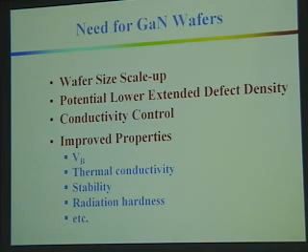Furthermore, the sapphire is not conducting, so both contacts have to be made from the top side. That requires more use of real estate. Therefore, you get fewer die per chip. The stress, the bowing, limits us now to about a 2-inch, or 50 millimeter wafer size. So as a result, again, our throughput will be low.